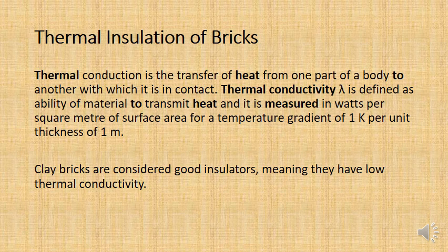So remember, insulation is the opposite of conductivity. It's how well a material stops the conduction of heat. And so the smaller that number, watts per meter Kelvin, that's how much power needs to be applied in order to heat one side of a wall by 1 degree Kelvin when the wall is 1 meter thick.